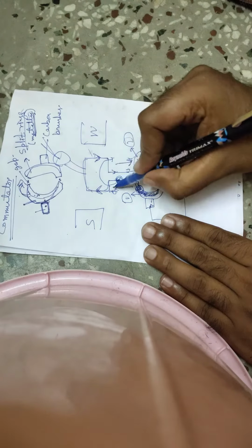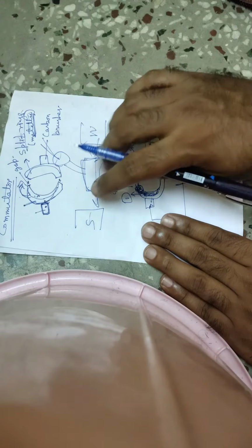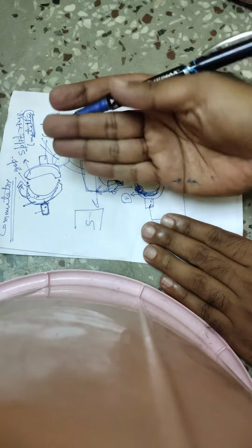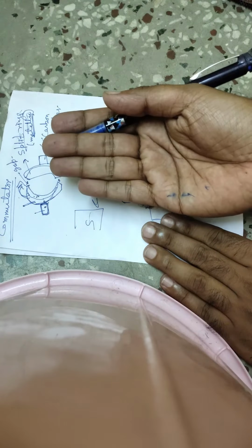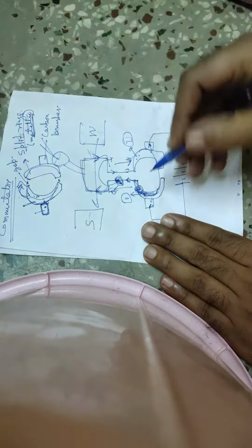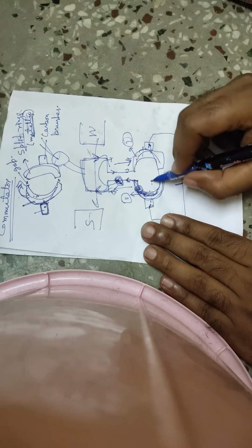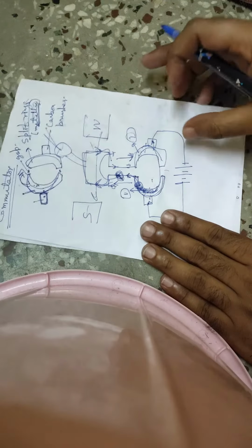How does a fan work? We took a current carrying conductor and placed it in a magnetic field, and force acted on the current carrying conductor. Because of the force it rotated, and the next time it started to force in the opposite direction, I changed the direction of the force itself, so it rotated further. And for that you need a commutator to change the orientation or direction of the current. Okay, so now I hope this is clear to you.